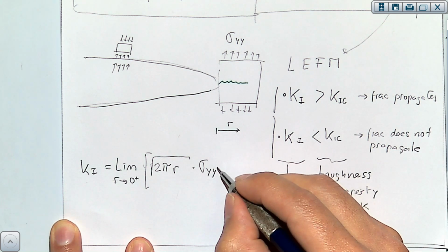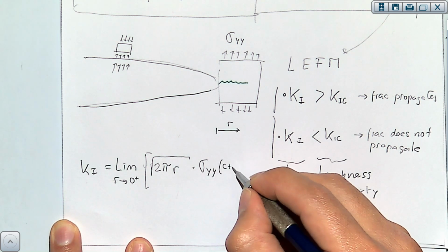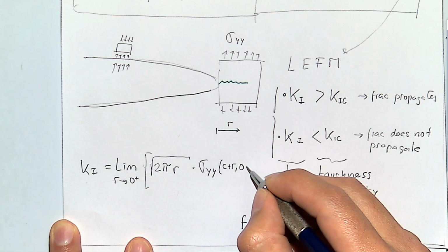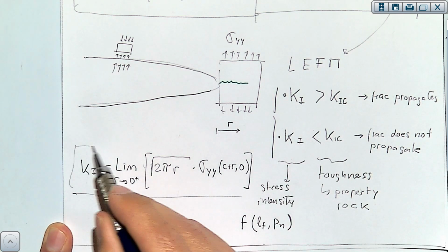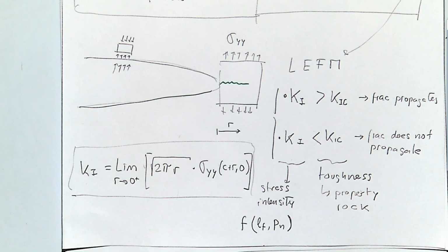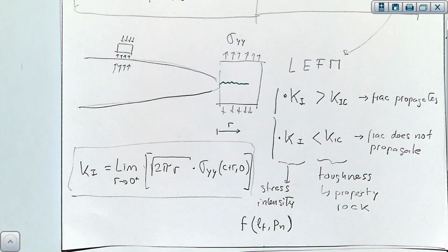Again, we're not going to talk in detail about this today, but we will on Wednesday. But the stress intensity factor is just a product of length and stress. And for these solutions of linear elastic fracture mechanics, when you make that product, instead of getting a value which goes to infinity close to the tip, you just get a value which is fine and it's not infinity.